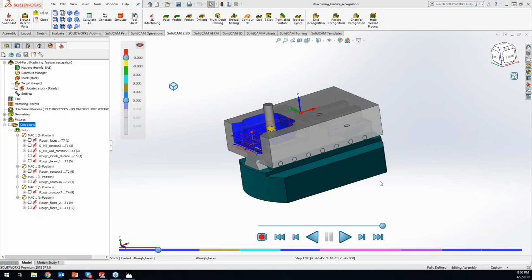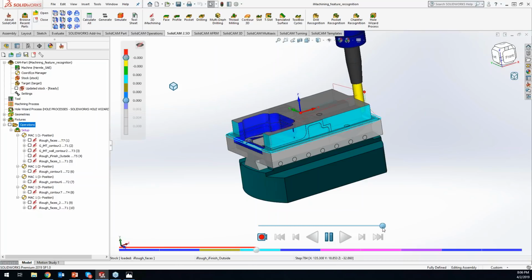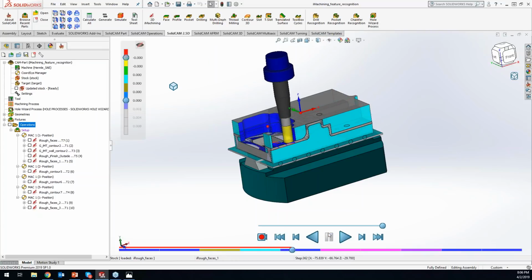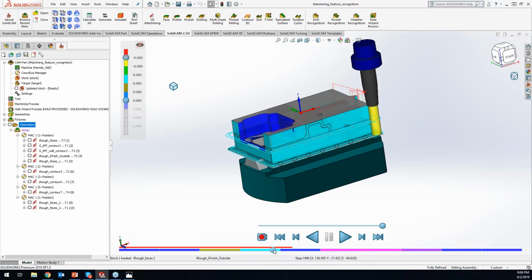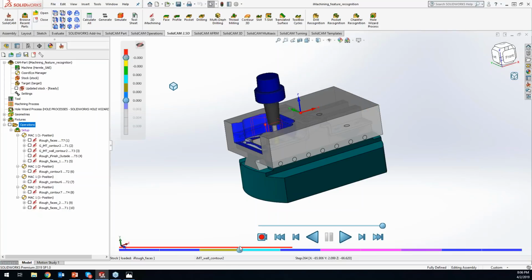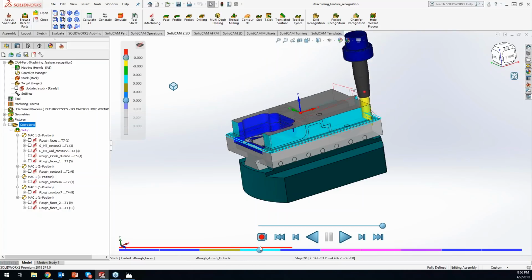Yeah, great point there, Greg. And as I'm going through this, you'll see that I have a red line down here. That's basically letting me know that I'm recording it. So what I can do is play this through as fast as possible right here, and we'll get through our operations. But let's say I get to right there. Oop, I need to stop it, and then I just want to rewind it. I'm just clicking and dragging this progress bar down here with the left mouse click. I can drag it back, and it's actually adding material back on there for you guys. So going back and forth.